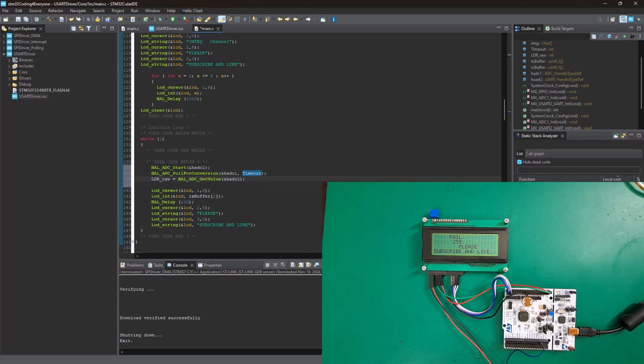Now the next thing we need to do is get the printf function that we're going to use to pass the message and the data that we're going to collect. That's very simple. We call the printf function, and the parameters will be the string LDR raw data, and the LDR raw data itself that we're collecting, formatted as an integer.